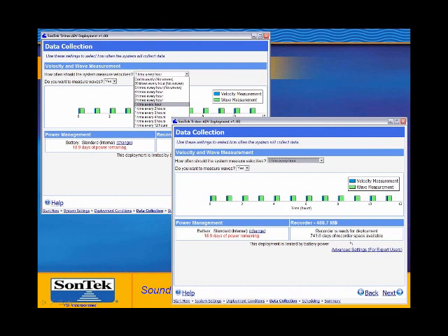I had another question from Kevin on if the Triton is capable of detecting if waves are breaking. In a nutshell, I guess no. The Triton will not be able to say whether the waves are actually breaking or not. It will give you the wave height and the period, of course, at that depth. So I guess just some little calculations post-deployment will be able to determine that. But as a direct measure, no, it will not say whether the waves are breaking or not.